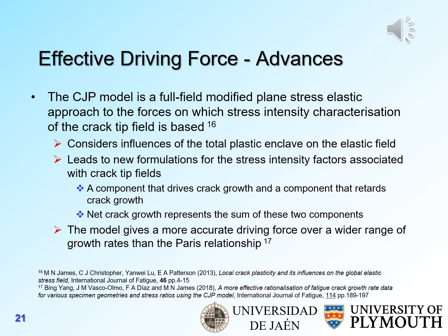What seems to be clear after a considerable amount of work with colleagues in Haiyan and in China is that the model gives a more accurate driving force over a wider range of crack growth rates than the Paris relationship. And while I'm on the topic of the Paris relationship, I would like to say that the Paris relationship is not a law. It is not based on any physical understanding, and physical understanding is the basis of a law.